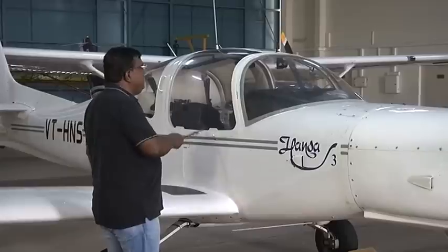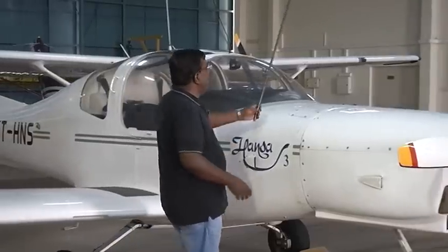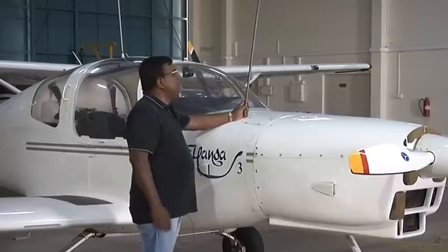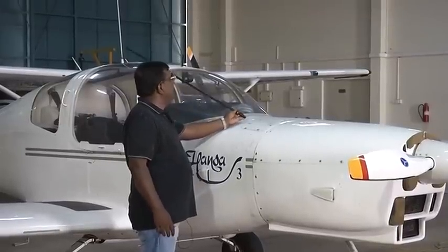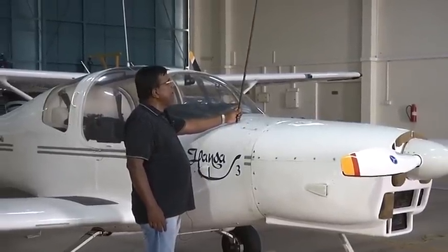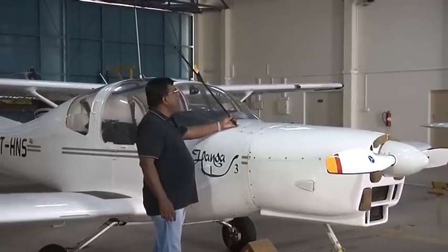Let us say the force on the fuselage is acting somewhere here. Okay? That is the lift. I am talking about the lift part. Similarly, drag will be acting like this, depending upon the velocity direction. Do not forget, lift will be perpendicular to the velocity and drag will be opposing the velocity.